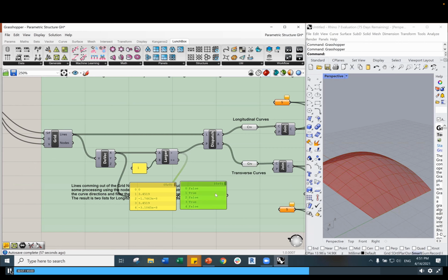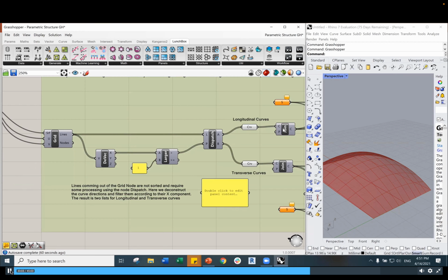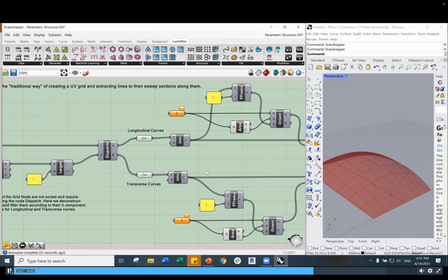Now, we're not done yet. There's another step we need to follow, and it's combining those curves. So I have a join. The reason for that is I just have all the segments, and that will make my geometry a bit choppy. If you look, I have 109, which means 110 because we start at 0. So I have a lot of lines, which are just all these segments, and I want to join them to have an easier way of using them.